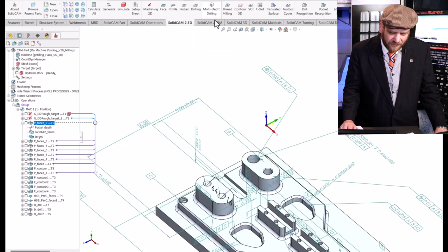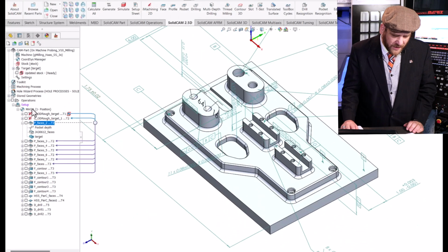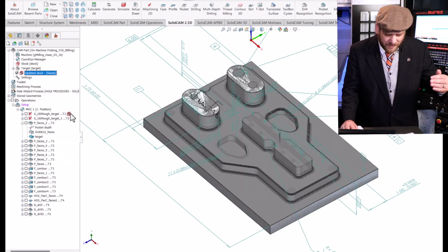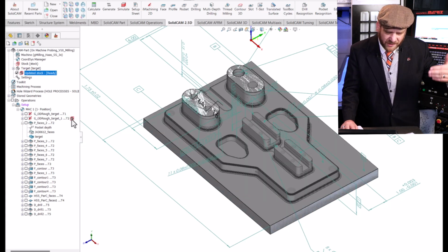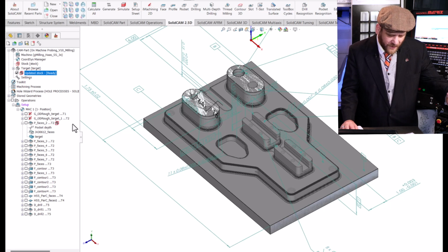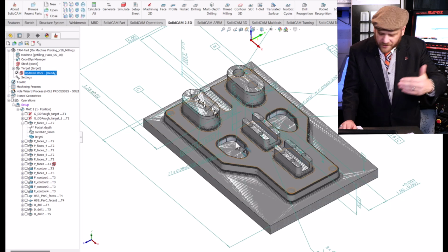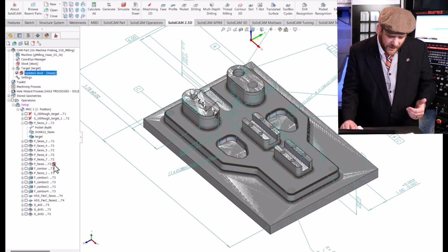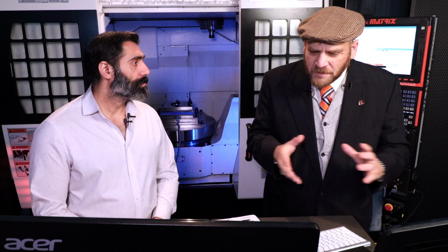And let me just show you what my final goal here is going to be. I'm going to use SolidCAM's patented iMachining to rough this out, which is an adaptive toolpath you'll see more about, and then some standard 2D toolpaths to cut through to a certain point, and then some cool, interesting drilling functionality and some toolpathing functionality to bring everything to within tolerance. So we'll get through that as we go here.